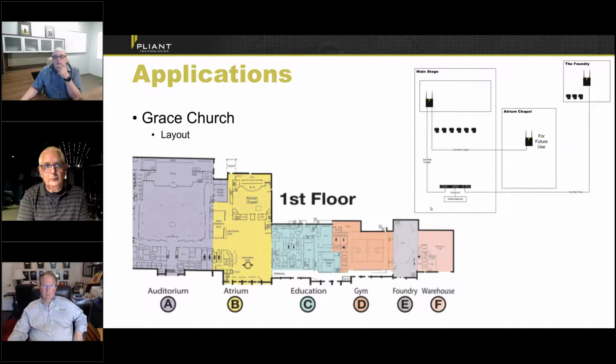David and I were discussing this the other day because he said he was hearing a little bit of echo, but he remembered that he actually moved the control unit. Yeah, and I didn't do the auto null. I need to do that. Yeah, so when you change the length of the cable, obviously that's going to change the inductance, the resistance, and the capacitance, so you need to do another auto null. But it works really, really well. As you said, basically in 10 minutes we were up and running, not only the wireless part of it, we were tied into his party line system very quickly.